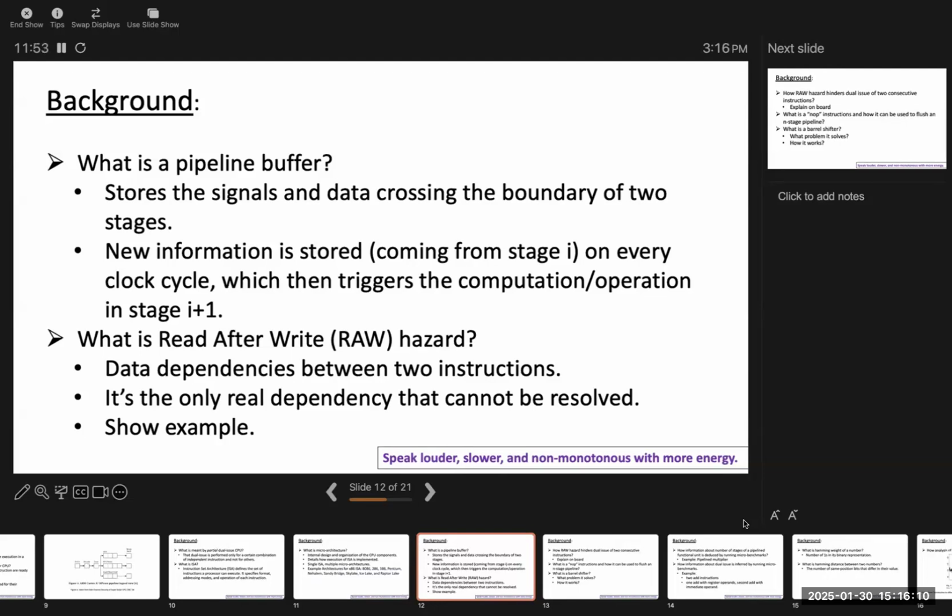It is just like that washer and dryer example which I mentioned last time. You have one bucket in the drying stage, and the second bucket in the washing stage, right? So maybe I have instruction 1 here, instruction 2 in this stage, instruction 3 in this stage, 4 here, instruction 5 here. But I don't want the fetched instruction to affect the decoding of the next instruction, which means this instruction should enter the decode stage only when instruction 4 has entered the issue stage, right? So in between them, I put buffers. The job of a buffer is to store your data signal, and the signal is propagated into the subsequent stage only when a clock signal arrives.